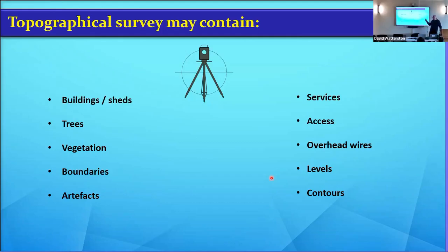But if you think that the ground is quite undulating and you want to do some remedial work, some design work, some changes of level, because you want to change that embankment, flatten it out and move it, then you want a smaller level grid. So you want it down to 2 meters or 3 meters. Or even a meter in some areas. So you get a level point every meter, which is a huge amount, which means you then know exactly how that land is lying. And from that in the contours, you'll know exactly what you're doing.